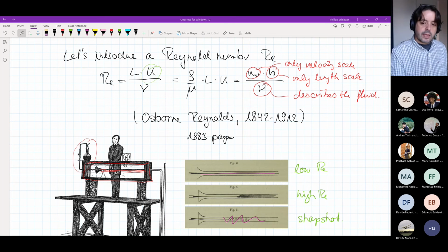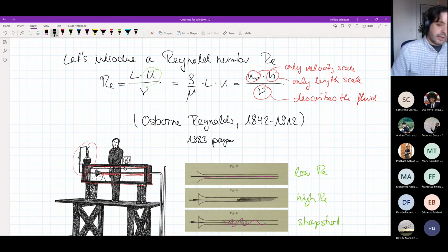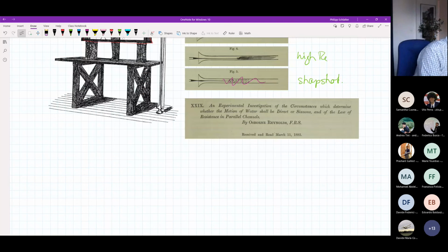Okay, but what does this have to do with us right now? Well, we have now introduced the Reynolds number in the way that it's done here, and as I said, you can view it, at least for now, as a non-dimensionalization of the viscosity. We'll talk more about that later on. Because we like non-dimensionalization so much, we can also look at the non-dimensional skin friction coefficient.